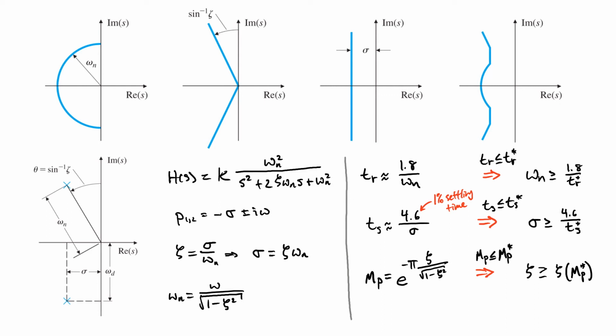In our motivating example for controller design to meet performance specifications, we saw a way of mathematically or analytically characterizing constraints on design variables. What we're going to see here is that we can map performance specifications back to closed loop poles and locations of closed loop poles in the complex plane that satisfy these various different performance specifications.